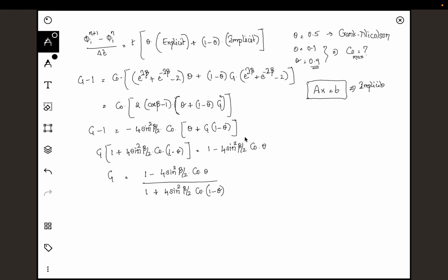So 0.9 is usually the one that I normally use, so that you have this computational versus stability trade-off in your control. Having a value close to 1 will give you computational efficiency, so it will be faster to solve, and having a value still less than 1 will ensure that the algorithm is also stable. So you're getting both these advantages at the same time.